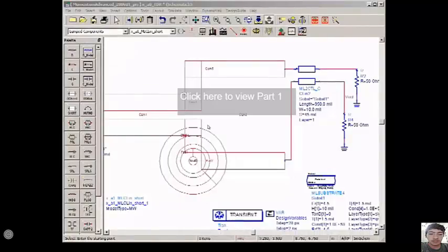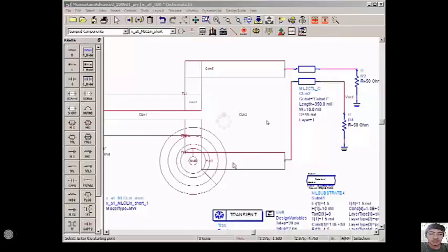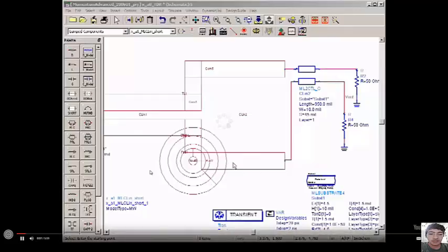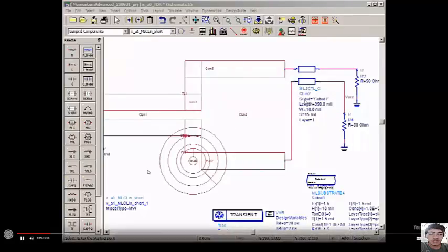So before I demo the channel simulator specifically, I wanted to show you one of the unique things about Advanced Design System that traditional SPICE-like simulators just don't have. It's something that's very important in the multi-gigabit regime. When the bit period is shorter than the flight time of the wires, the ends of the wires aren't at the same voltage anymore. They behave like transmission lines, and you have to model these distributed effects, microwave effects if you like, at the level of the physical layout or the artwork.